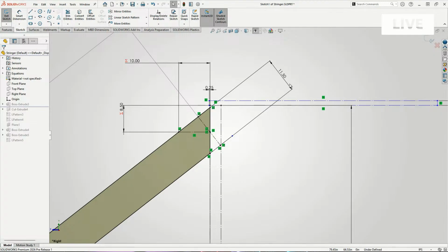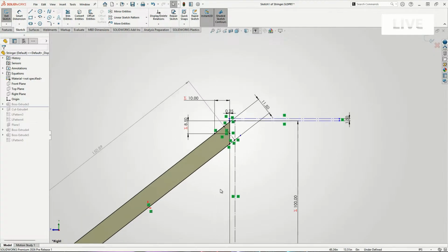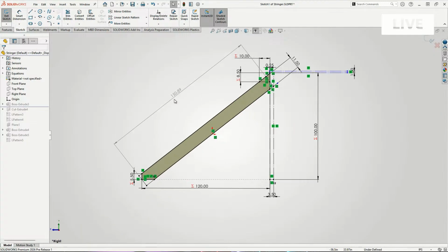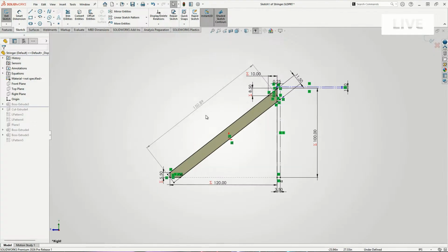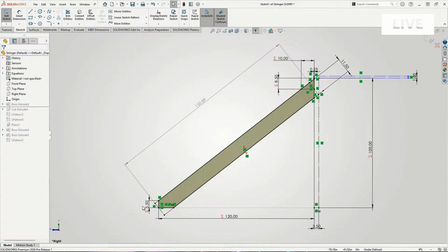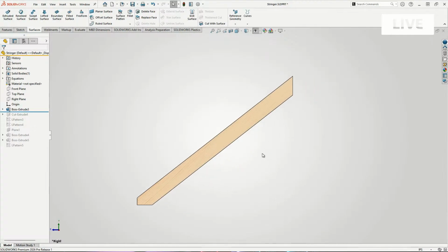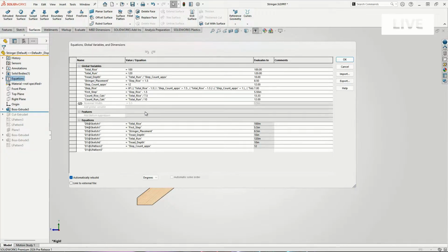11.5 is my bottom stringer, my raw lumber. So I have that as well. If you're doing a 2x, that'd be a 2x12. If you're doing a 2x10, which I don't think is by code, I could change that. But yeah, there are some basic dimensions that aren't variable driven. And then here's 150, 89. This is just a driven dimension. That's why it's gray. That driven dimension is giving me, not quite the stock, but I wanted to get the bounding box. And I could get that from the bounding box option in SolidWorks. Okay, so that was the first thing: give me some equations that are driving the rise and run of the stairs, and let the relationships figure out some of the main cuts. So let's go in those equations and look at it.